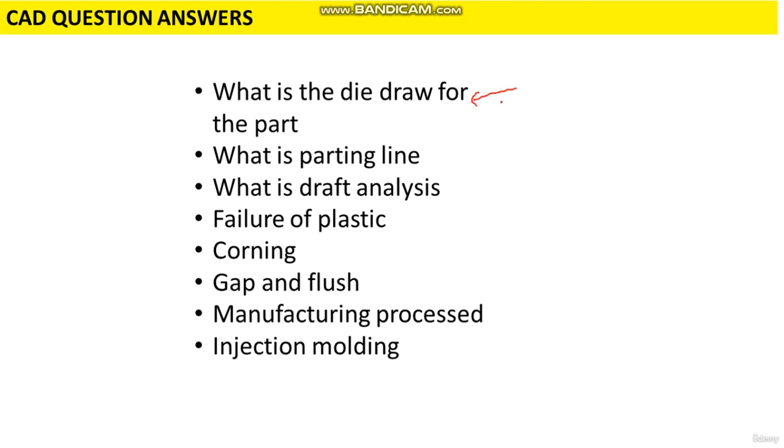Die draw is your tooling line, your main tooling direction, called MTD, and the same line will be the injection molding line, and then the parting line for the part. Then if any lifter or slider is coming, then the slider line and lifter line for that part.